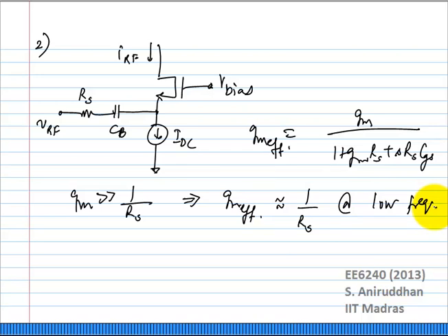You understand? I am applying it through a resistor. So the effective current into the common gate would have been VRS over RS plus 1 over GM. Okay. If I make 1 over GM very small compared to RS, it will just become 1 over RS times VRS. And all of that current flows through the common gate into the output. So of course you can put in the sign this way because you are applying a voltage and creating a current.